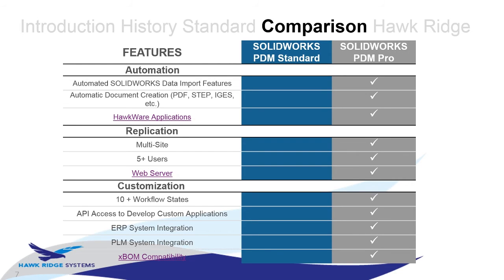Okay, we got a new revision. Let me time myself finding my file, opening it up, doing a file save as to a PDF, setting all the options, and then pointing it to wherever it needs to be converted to. That could be a shared drive, a local drive, or something like that. PDM Pro can now automate that entire process. So with PDM Pro, every time your drawings get approved, and only when it gets approved, no other time, it'll find those drawings with a new revision. You can even have a watermark that clears out of it, and it'll automatically convert it to a PDF in some location.